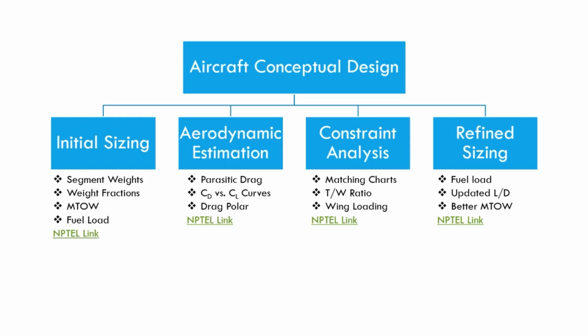Then we have refined sizing, in which you calculate the updated L over D values because you now have T/W and wing loading. So you can get a better estimate of max takeoff weight.